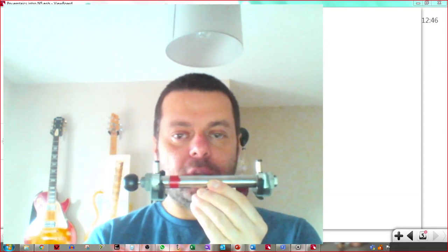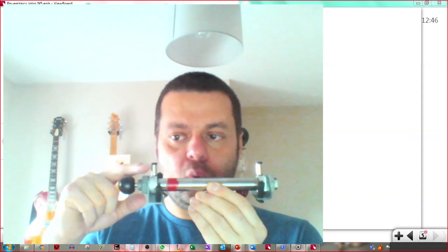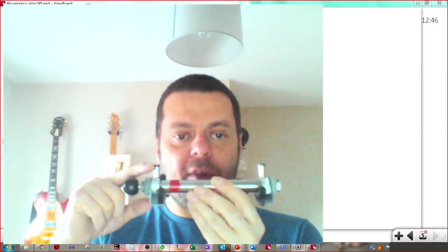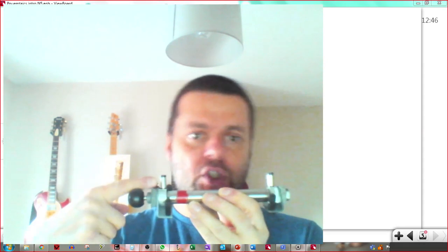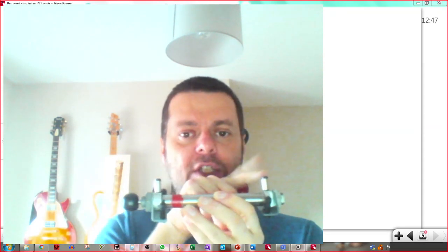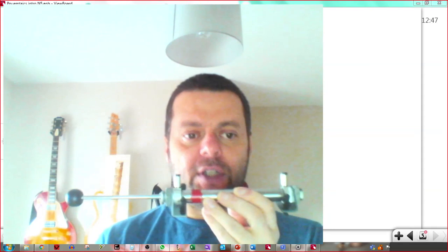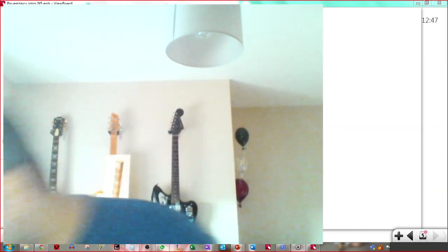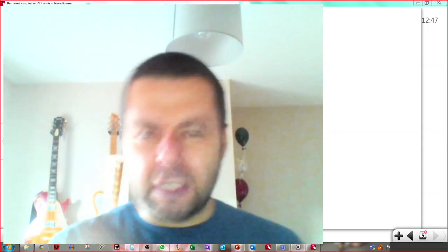So you can show it in-stroked with the two ports, port 1, port 2, these bits sticking up. That's the port sticking up there. You might refer to that as the in-stroke port, because when you apply air pressure here, that's going to in-stroke the cylinder. You refer to that one as the out-stroke port, because when you apply air pressure to that one, the cylinder will out-stroke. Okay, so sketch that one and label it. I'm going to want to see these. Do them clear, do them carefully.